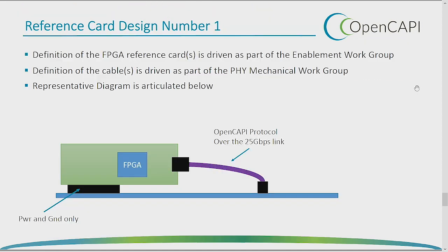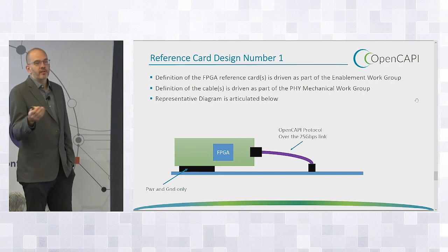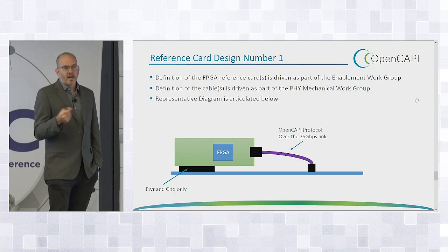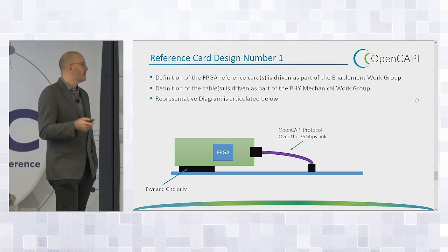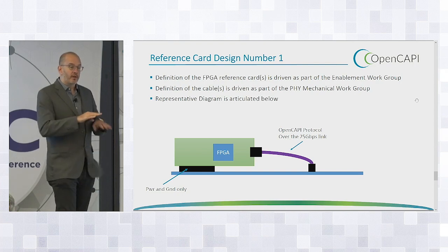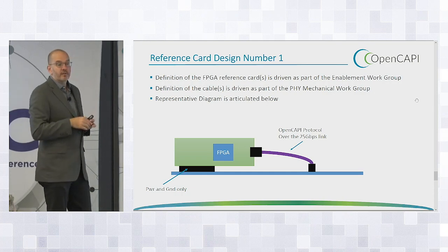Talk a little bit about what these things look like. We found that running this high-frequency interface, we typically want to do through cabling solutions. The motherboard, if you're going to run 25, 32, 50 gig, the material becomes more expensive. And so we're kind of trying to borderline between, do you want to do all cabled solutions, right? That way your motherboard can just be power and ground.